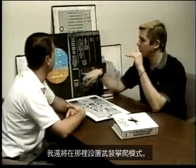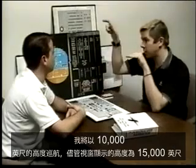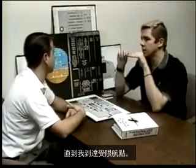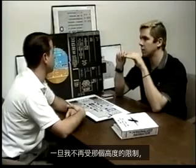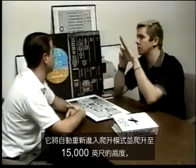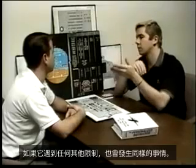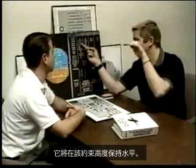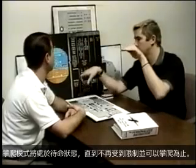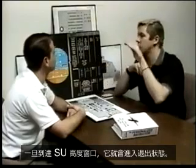I'll also have an armed climb mode there. I will cruise then at 10,000 feet, even though I have 15,000 feet in the window, until I reach the constraint waypoint. Once I'm no longer constrained at altitude, it'll automatically re-engage climb mode and climb up to fly to the 15,000 feet. If it encounters any other constraint in there, the same thing will happen. It'll level at that constraint altitude, the ALT CST will be engaged, and climb mode will be armed until it's no longer constrained and can climb up. Once it reaches the FCU altitude window, it then goes into ALT.